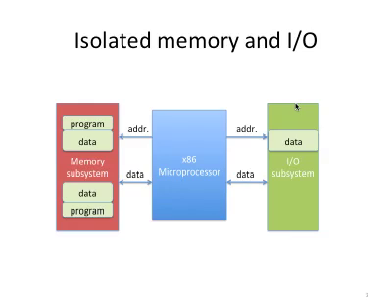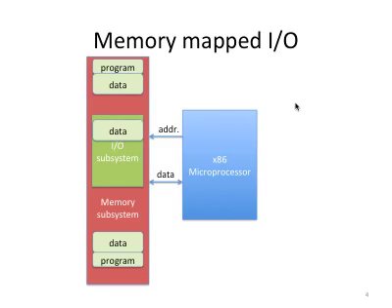You have the whole memory address space, which you can use to access memory chips. On the other hand, with memory mapped I/O, part of the address space is going to be reserved for I/O devices, so the whole region cannot be mapped to or used by memory chips.